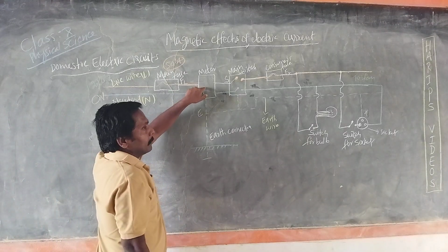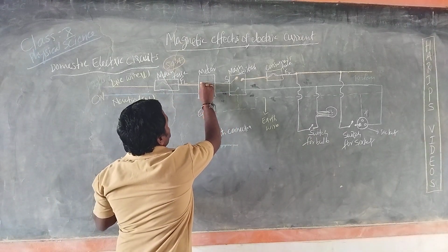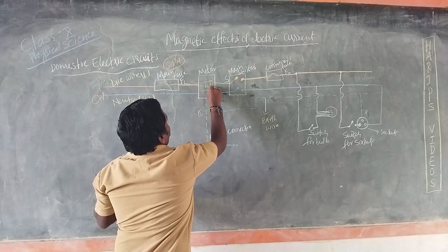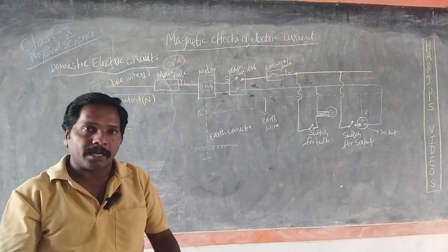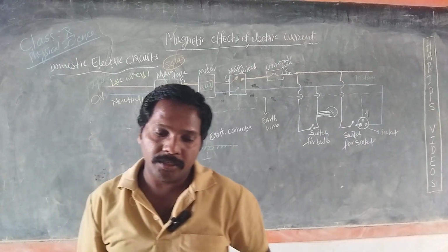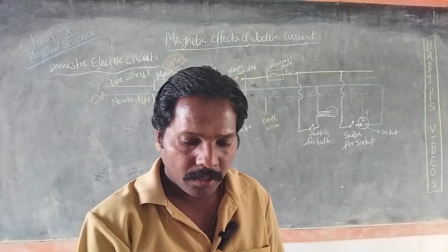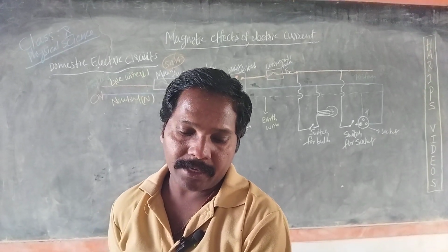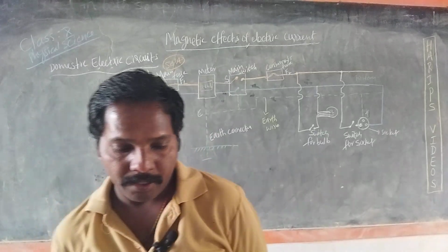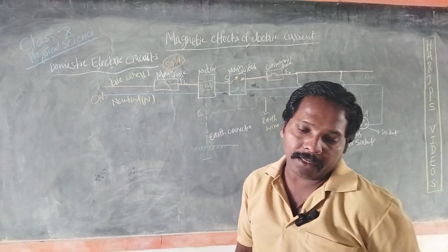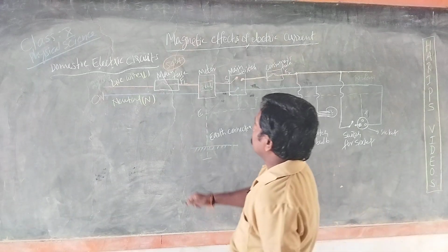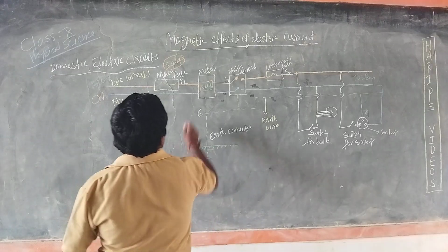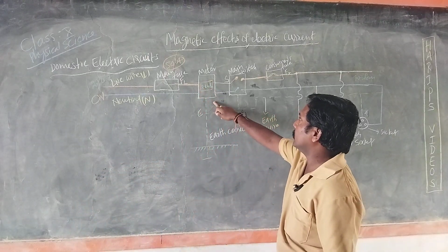The wires then go to the electric meter. The electric meter tells us how much electric energy we consume. The main fuse F1 is put into the live wire. This fuse has a high rating of 50 amperes. The two line wires then enter the electric meter.